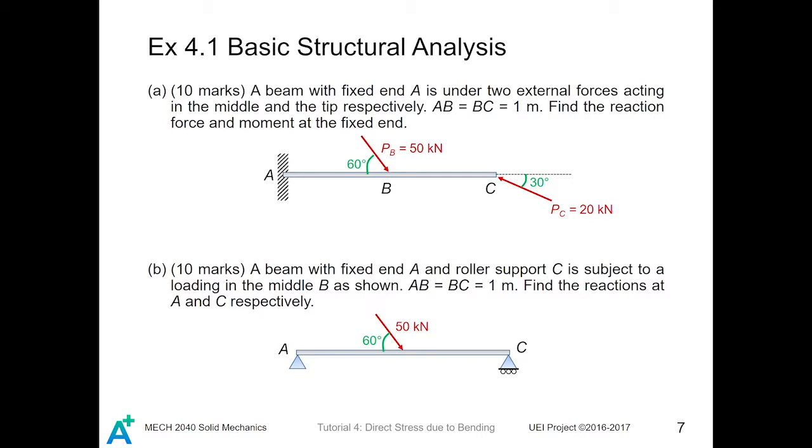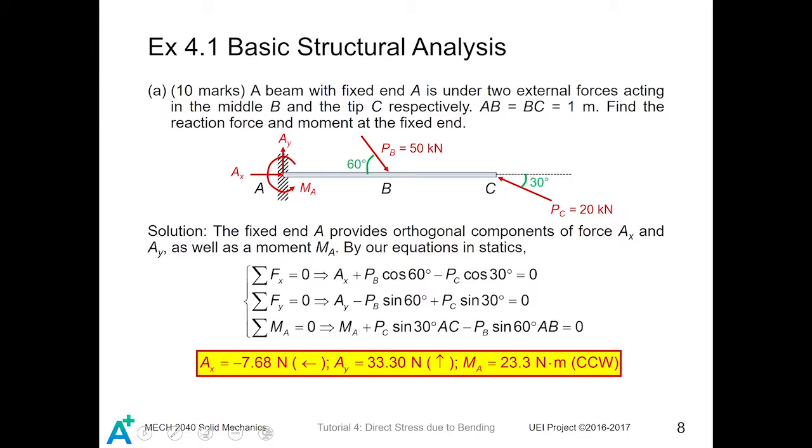Besides, a beam with fixed end A and the roller support C is subject to a loading in the middle as shown here. If AB equals BC equals 1 meter, you are required to find the reactions at A and C. For the first problem, first sketch the orthogonal components of forces as well as the moment at